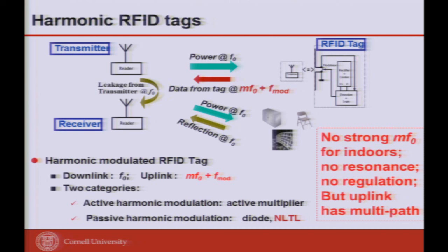Subharmonic is much harder to filter, right? Because it's too close. You need very expensive, high order filters. But to filter the signal in the second or third harmonics is very simple, because it's far away. So most of the self interference and all the reflections are, to first order, gone. Unless you have nonlinear materials at these frequencies, they're not reflecting in the second harmonic.